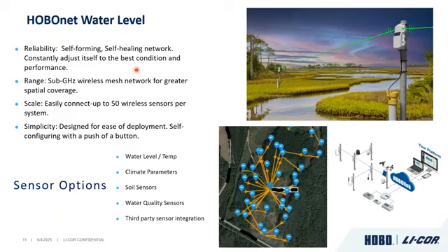We have soil moisture sensors, multi-depth ones that do EC, temp, and moisture. You could also do third-party sensors or water quality sensors. You can tie this all in to create this large mesh network of sensors and filter that back to one main hub so that you can really drive that cost down and scale your site affordably.